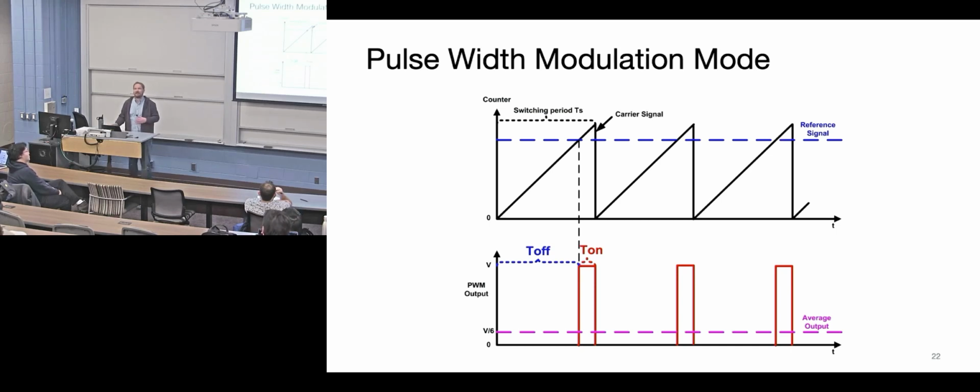That's a good question. I think you have to think a little bit about what's the device you're trying to drive. But let's say it's an LED, and it's a very precious LED. Maybe it has a threshold to turn it on, but oftentimes LEDs or diodes or some of those passive devices will say it can take pulses of a certain amount of energy for this long, and average energy is this long. So you do have to read through your data sheet to figure out how to control this device. That doesn't really answer your question. Does that make sense?